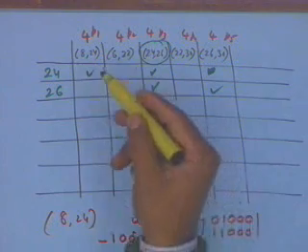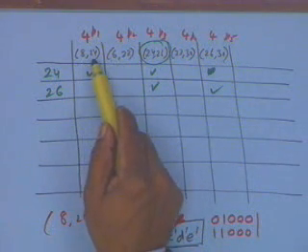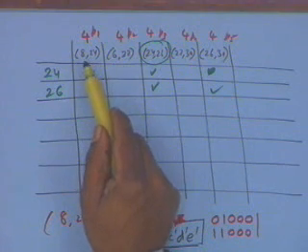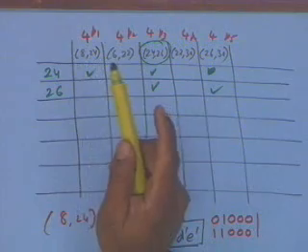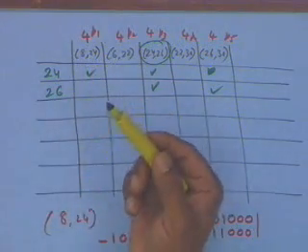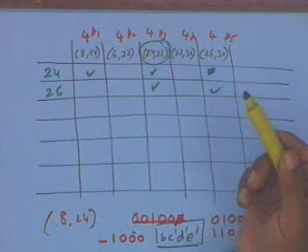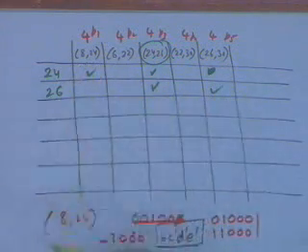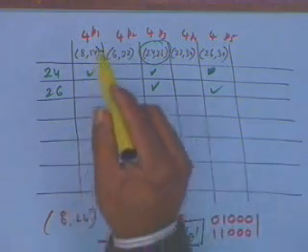And this cost is very clearly determined by how many minterms are present over here. If it's a single minterm the cost is 5. If 2 of the minterms are present the cost is 4. If 4 of the minterms are present the cost is 3, and so on and so forth. If 8 of the minterms are present then the cost is 2. The cost of the prime implicant depends on this. Now what happens?